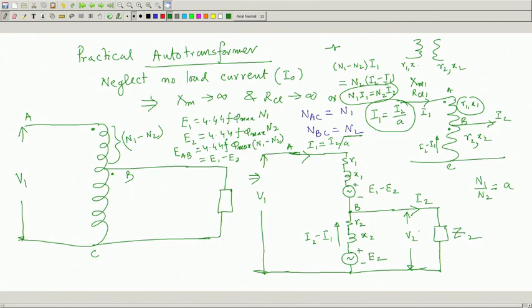Acha. Now, this voltage is V 2 and this voltage is V 1, applied voltage. Terminal voltage, induced voltage, they are not now same, there will be a little drop here. But this tells me that the voltage across the so called AB portion of the winding must be V 1 minus V 2, this voltage minus this voltage, with this side plus and this side minus.